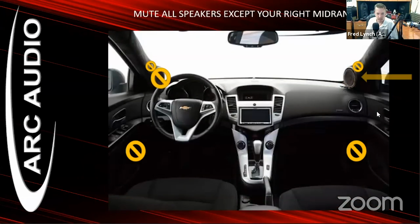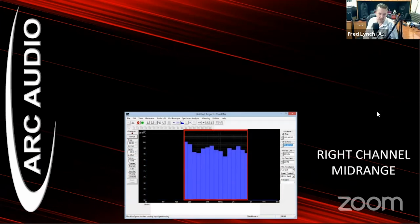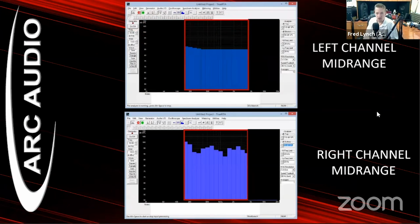Now we are going to move on just like we did before on the tweeters, and we're going to mute the left mid and unmute the right mid. And of course, here's our response. We're going to isolate the frequencies for what we're visually seeing. This is the crossover range of that mid-range driver. We're going to reference back to our left channel that we've already EQ'd. And now we're going to EQ the right-hand side as well. And that right-hand side driver now matches the left-hand driver.